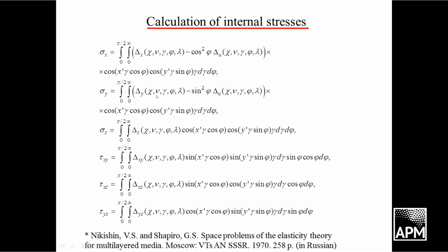And that's why we can approximately use such relations with parameter C, which is the ratio of elastic modulus of the layer and the substrate, for calculation of stresses inside the layer. This layer is more rigid, but really it is not absolutely rigid. So we use this as an approximation.